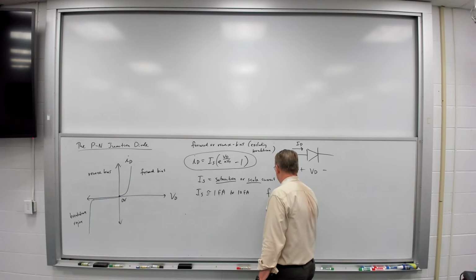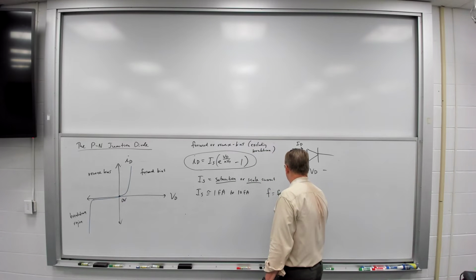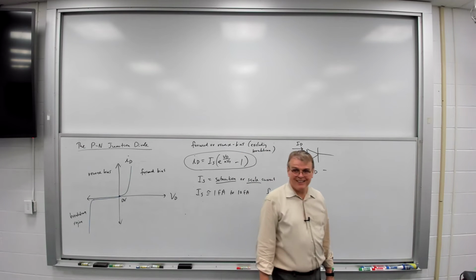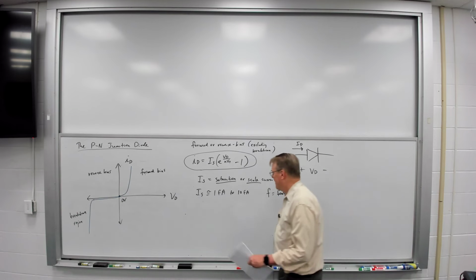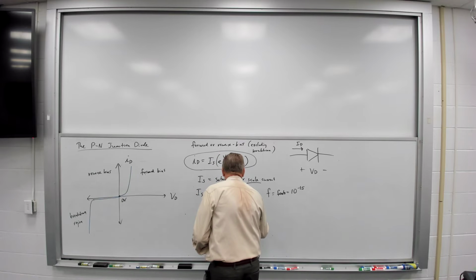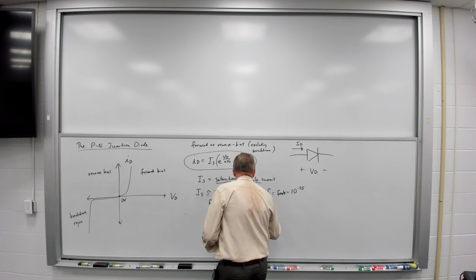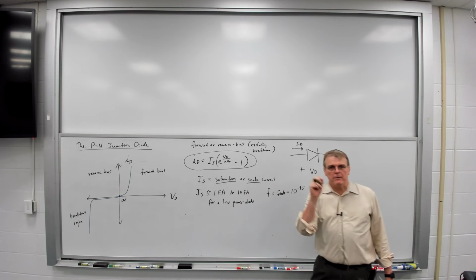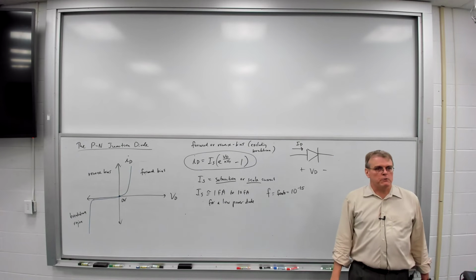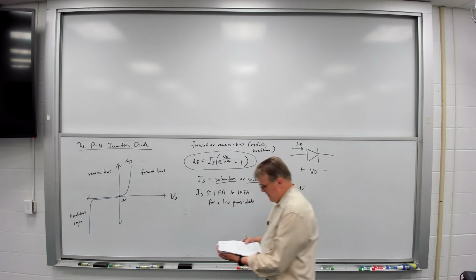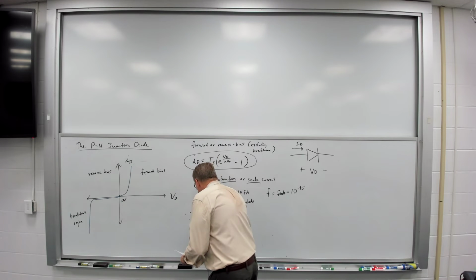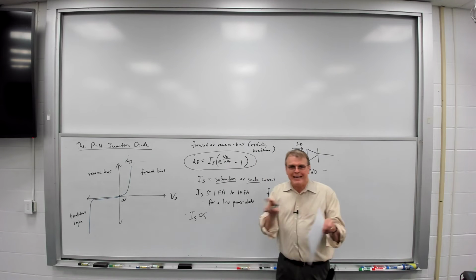And what's a femtoampere? 10 to the minus 15. It's small. So that's a very small current. So for example, if you've got a diode that's constructed on a semiconductor for an integrated circuit process, that might be a very typical value for the saturation or scale current. Now I sub S, in this case, is proportional to the p-n junction area.